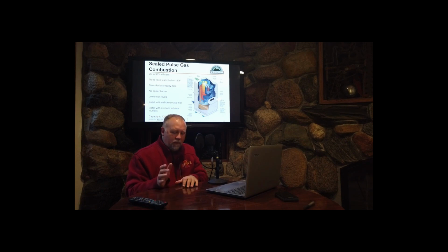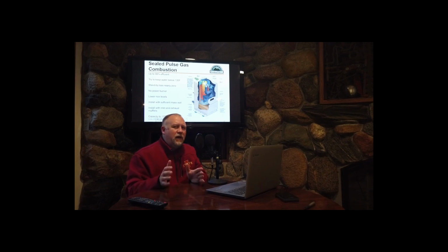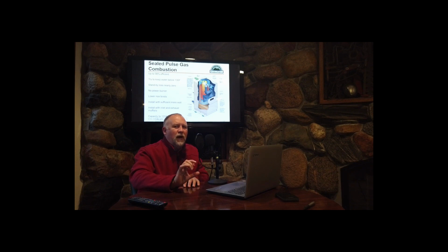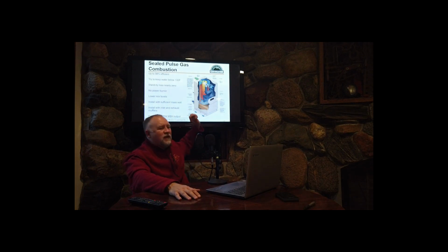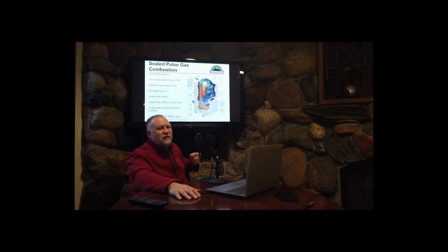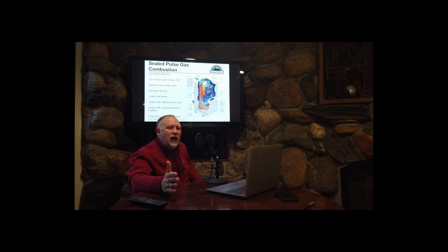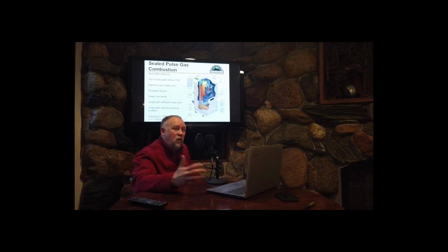In other words, if I want to maximize the Q, the heat transfer, I have to look at the other side of the equation, the U value. Well, how do I improve the U value? And in this case, improve means how do I increase the U value, lower the resistance? For a wall in a building, I want increased resistance because I don't want heat transfer.